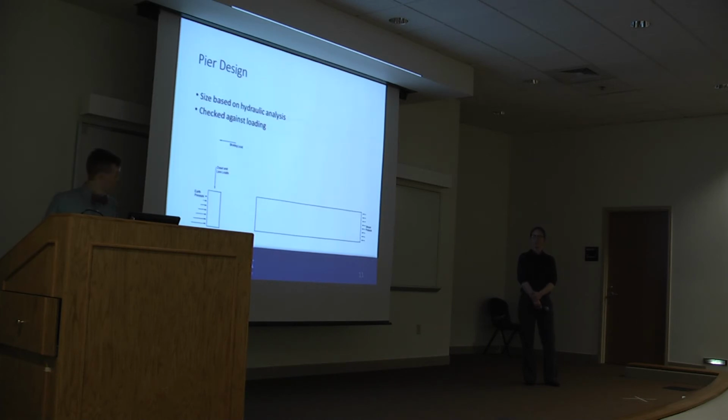The one on the left was the controlling state where we had the pier acting as a retaining wall, holding in the earth from the stream. We also, on that, had the dead and live loads on top of the pier, plus the braking load acting 6 feet above the pier. The stream pressure on the right did not control because the stream didn't move fast enough to cause a big enough pressure.